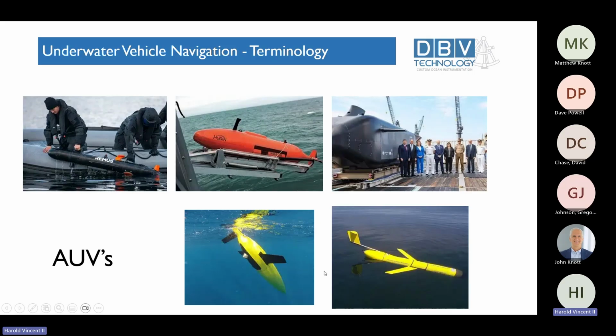They do not move through the water using a conventional electric motor turning a propeller to get propulsion. Instead, a glider will start at the surface, become negatively buoyant, and change its ballast so that it's pitched downward. And then it sinks through the water column, but moves horizontally while it's moving vertically.